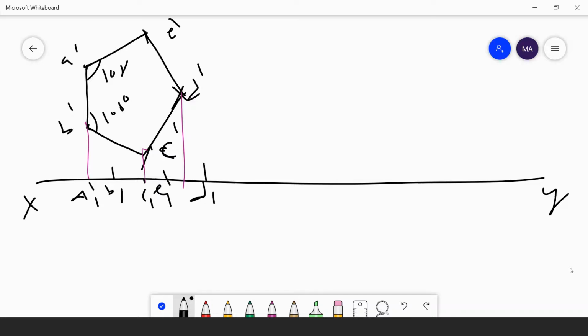After that, he has given the inclination: the surface is inclined at 30 degrees to VP, which means draw the inclination in HP. So I am drawing the 30 degrees inclination in HP.